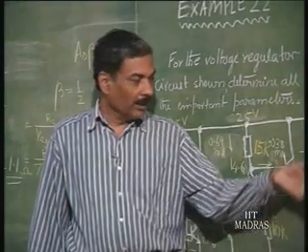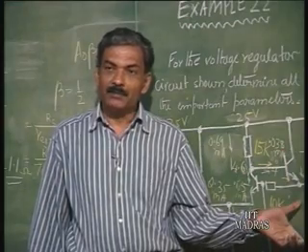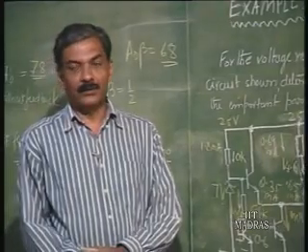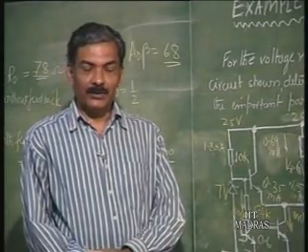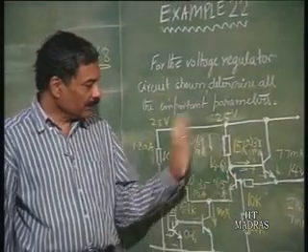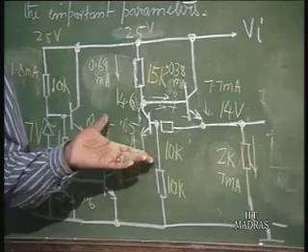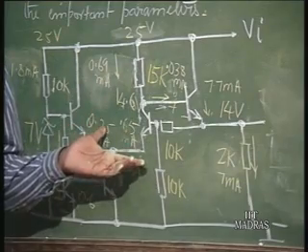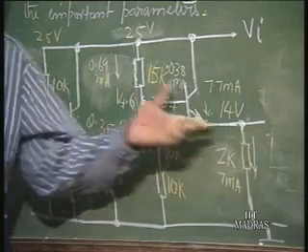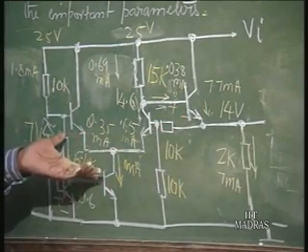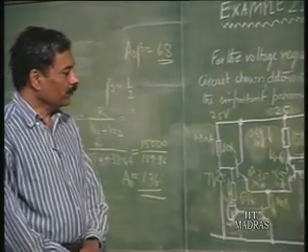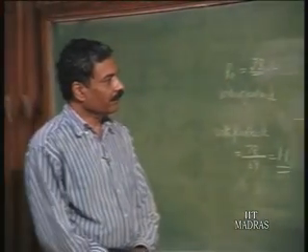So, that output impedance may become pretty high and it may cause problems, unless you purposely reduce it using a special technique. Like now, if it does not use an op amp, the output impedance at low frequency will be almost the same as the output impedance at high frequency. The moment you use an op amp, that gets drastically changed. So, output impedance is evaluated.